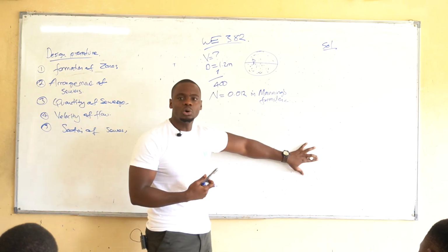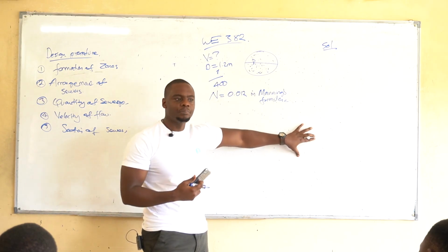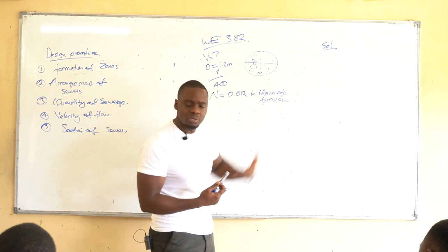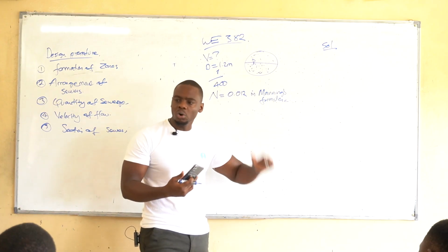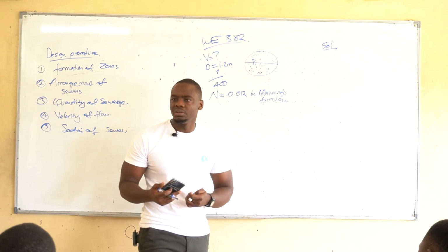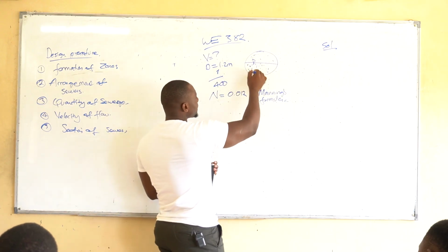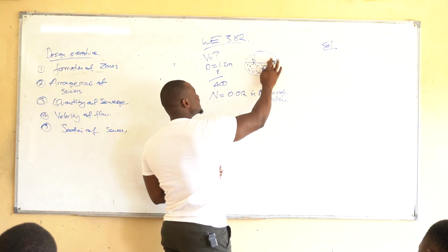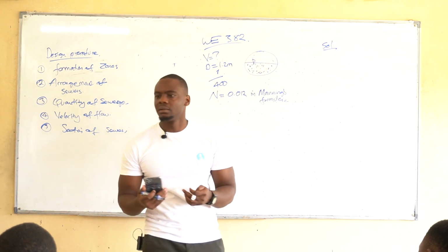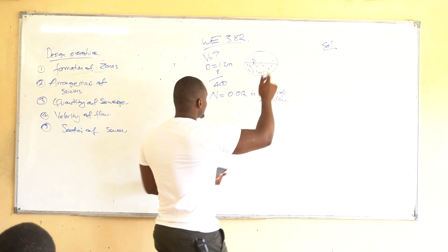And talking about this topic, whether the question has stated it or not, this is just something you need to know as an engineer: our pipes transporting sewage are always at half full, unless I've stated the value. If I haven't stated it, then you always consider that. So you've got your fecal waste running, and then the rest is left bare just to avoid clogging. We good? Okay.